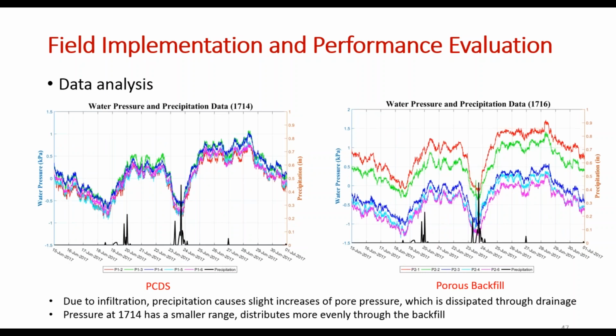So here are some close-ups of this data. On the left is from the abutment with PCDS. On the right is with the porous backfill. So we can see that there is another trend: after a precipitation event, the pore pressure will increase. That's because infiltration occurs.